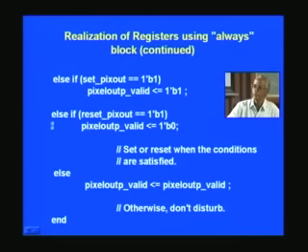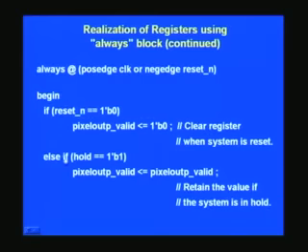And now you have seen that if, else if and finally else structure. If you just count 1, 2, 3 here and 4 and 5, from my experience, if you exceed this 5, your speed of operation will get hit. For example, if you are aiming at 100 megahertz operation on an FPGA, let us say field programmable gate arrays.